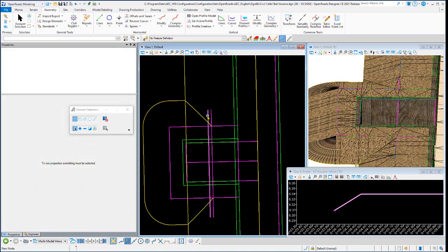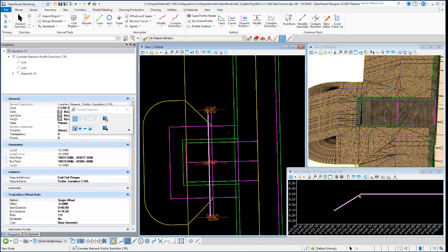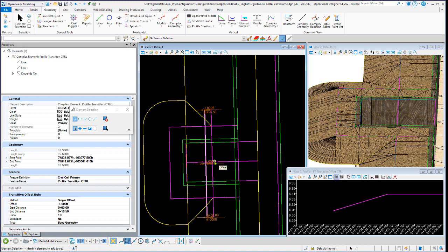And then this element here. If I change this offset, here's 2% off of this. This is really just a transition from the 2% off your primary to the 2% off your FP here. So you can ultimately flatten this out a little bit. If we change that offset to -1, watch the profile. That should adjust and flatten that out. So you can control that transition from the 2% off of there to the 2% off of there, like I just did.